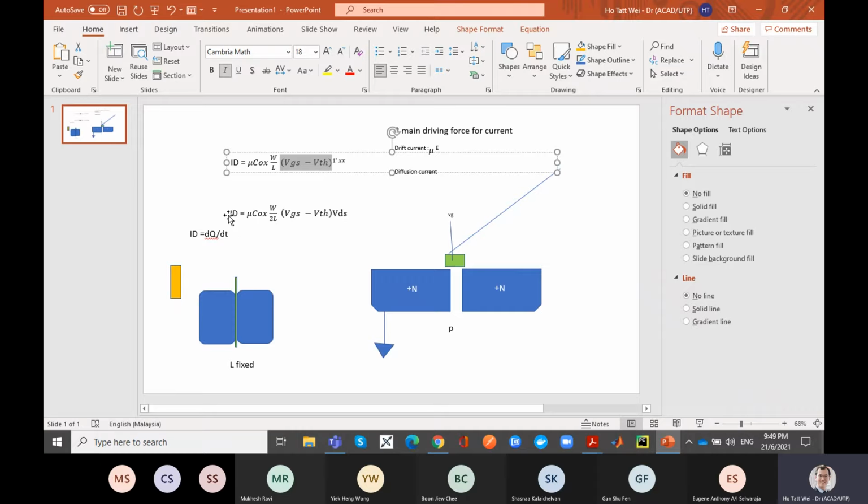And I'm asking you to quantify all of this, because you're going to say, okay, VTH varies by 10% or by 20%. How much does the current vary? If you know this 10-20%, how much the current varies, that's the percent change in drive current. So this is the variation in speed that you will expect in your chip. And if VTH changed by, again, 10-20%, how much does the subthreshold leakage change?